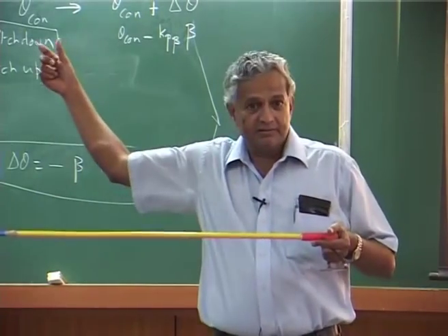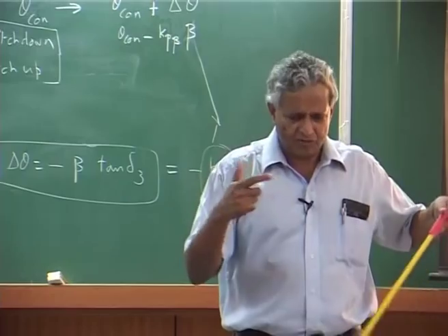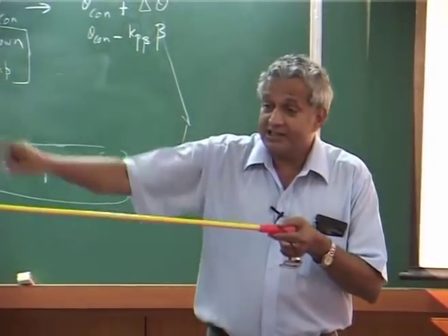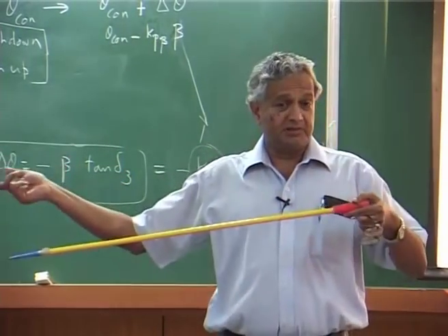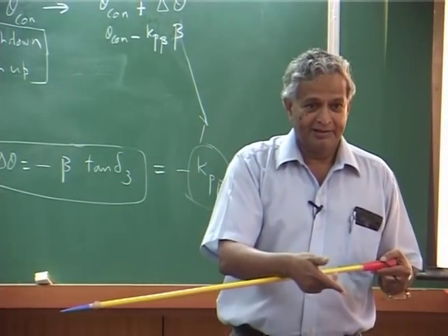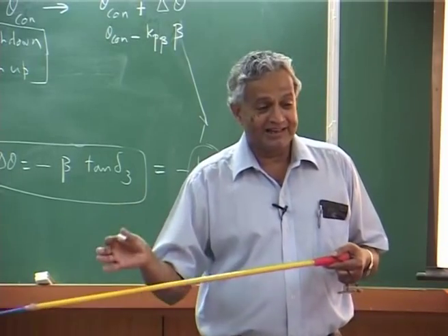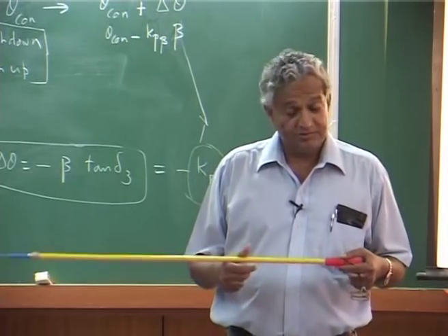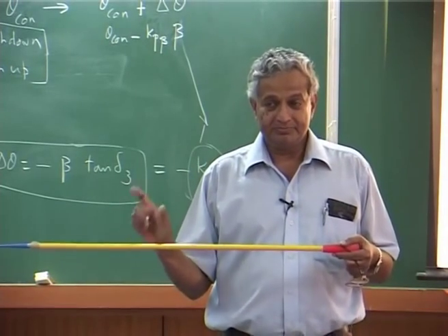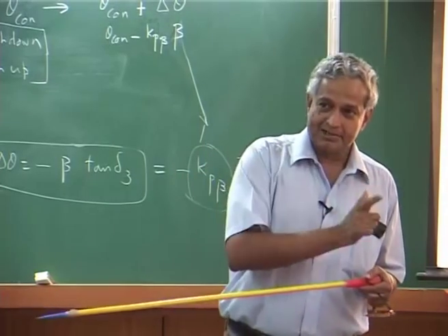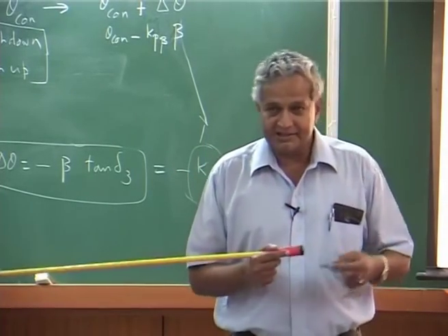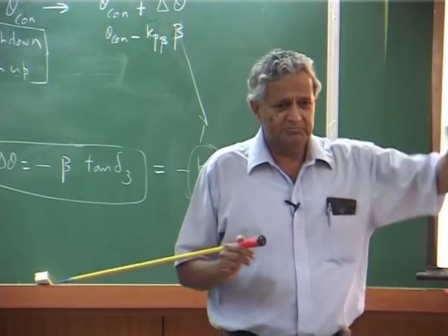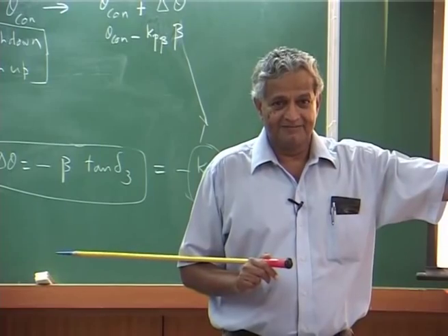because the deformation you introduce intentionally, you would actually unintentionally, I would put it, and that depends on what is the elastic deformation of the blade. Elastic deformation depends on what is the load. So, it is very tricky to say what exactly is the deformation you will get, the coupling, but one has to know that this effect occurs in those blades, because you may think that this is what the blade angle etc., but actually what you may get is maybe totally different in operation.